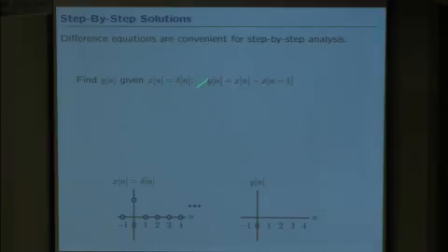So given the difference equation and the input signal, all we need to do is sequentially go through the different values of n and think about the implication of the system on that input. If I use the value of n being minus 1, this general form of the difference equation tells me that the output at minus 1 is related by this difference to the input. So y of minus 1 is x of minus 1 minus x of minus 2. Since both of those are 0, the output at time minus 1 is 0. Trivial, right?